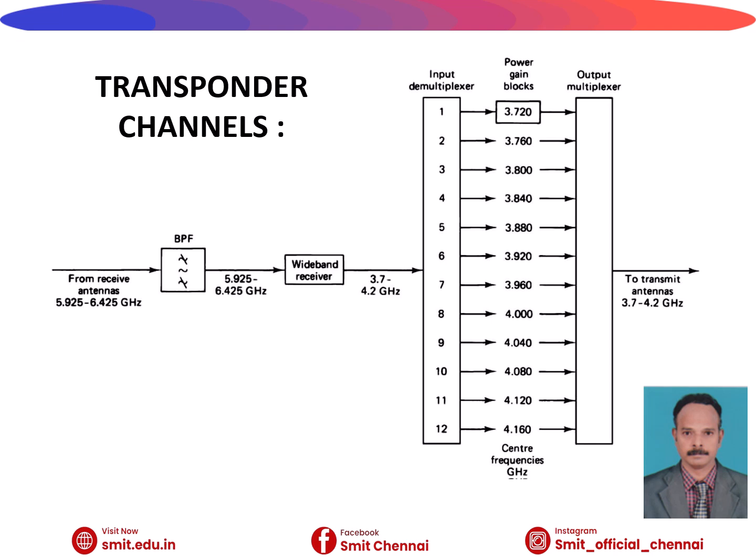These are the various transponder channels that can be transmitted and received at the various frequencies depicted in the diagram. We receive the signal from the antenna and we transmit the signal from the antenna. In between, various processing steps are carried out. The important building blocks are the BPF, the wideband receiver, the input demultiplexer, the power gain blocks, then the output multiplexer. The wideband receiver, as the name indicates, improves the bandwidth of the signal as well as enhances its quality. That is the main purpose of the wideband receiver.